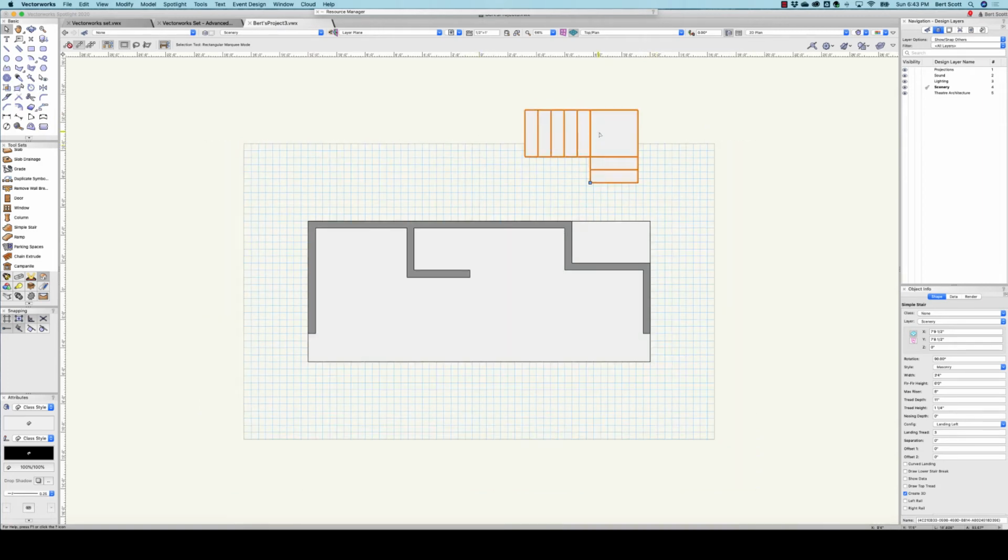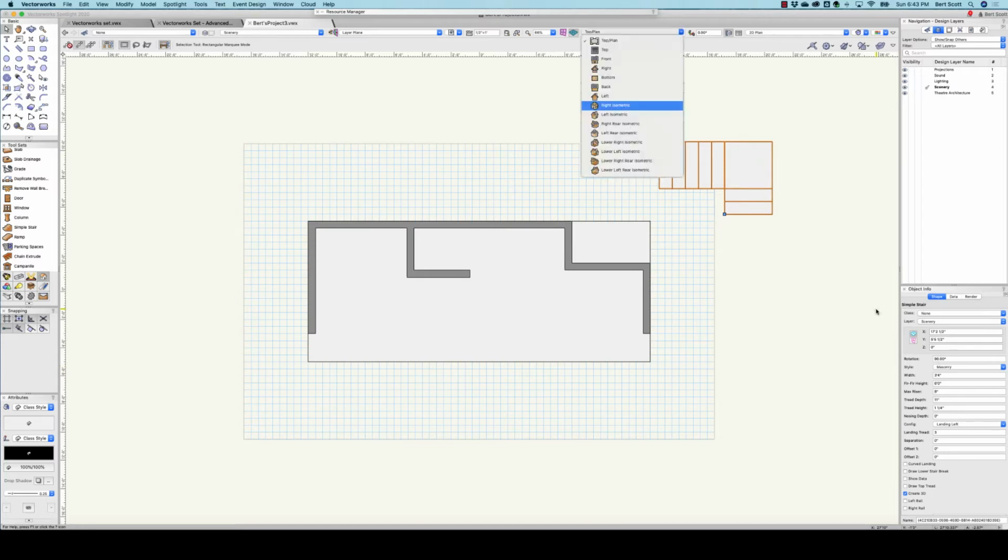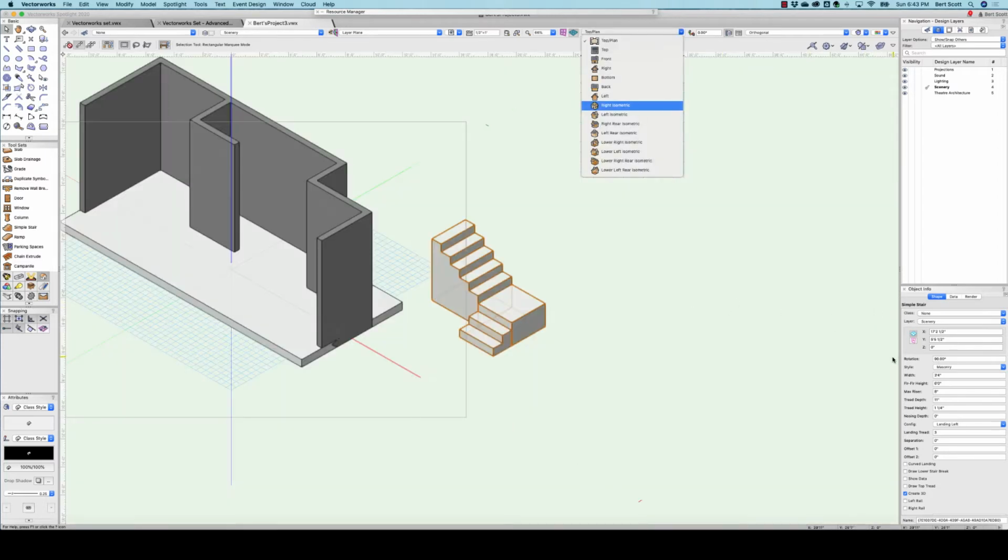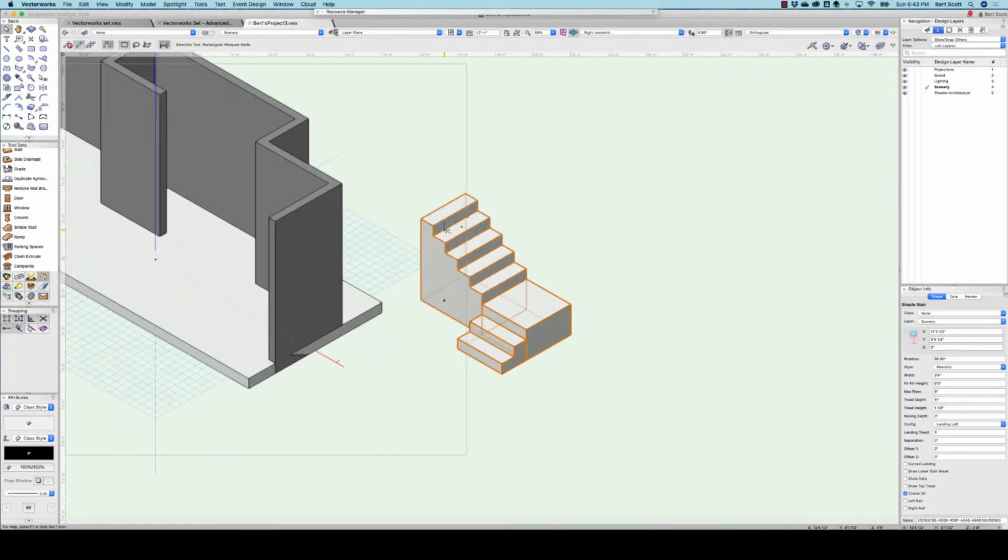To talk about the masonry and the other style questions, I'm going to go to an isometric view so you can see that masonry gives you just solid stairs as if they were solid concrete, hence masonry. Standard gives you sort of solid stairs, but that don't go all the way to the ground.